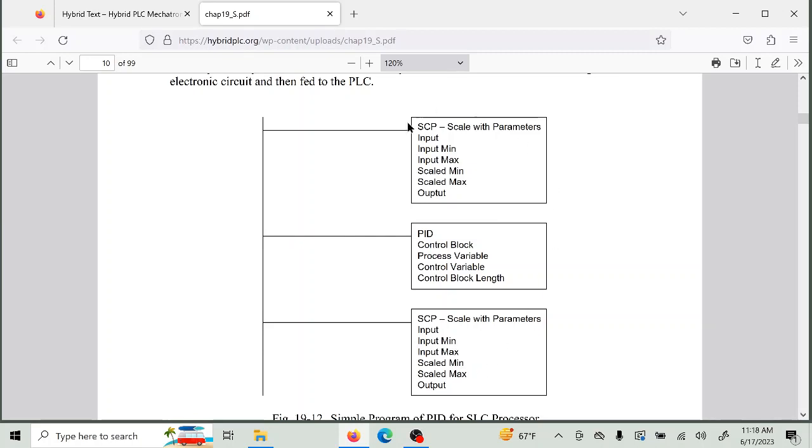So whether you have to do this inside the PLC (Siemens makes you do this inside the PLC), or whether you do it when you're scaling your input card and your output card, you have to do it. So here was the first one. Scale the input, do the PID, scale the output. Now, where is the auto in the manual? I didn't have it yet, but this is the beginnings. So I had the auto manual just by being able to click on this screen and set it up through the screens. But at least I had the ability to do that.